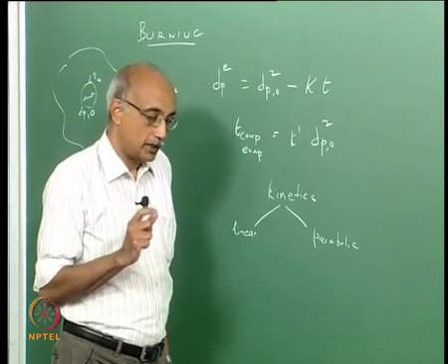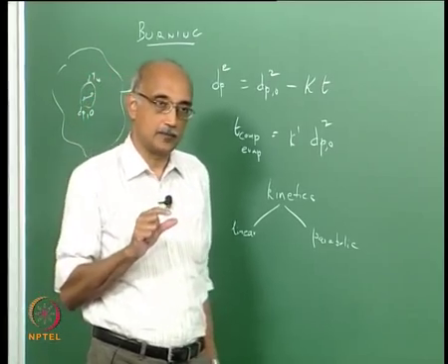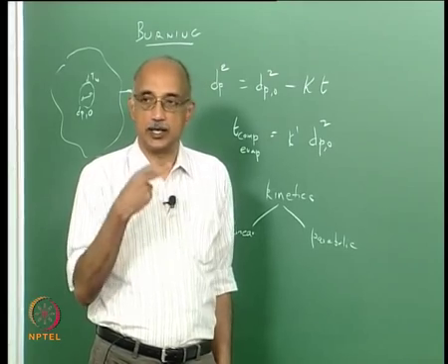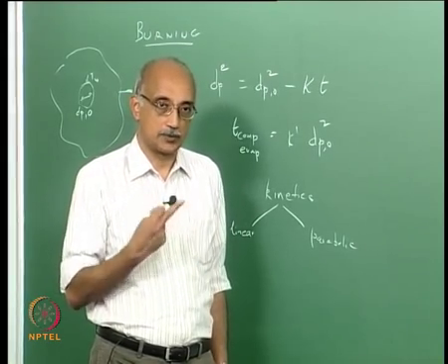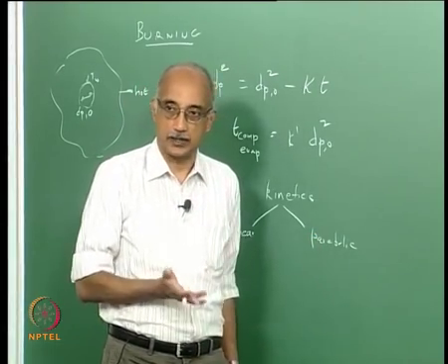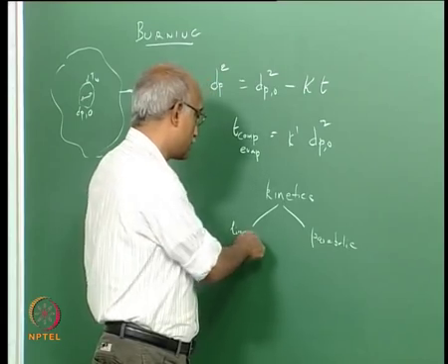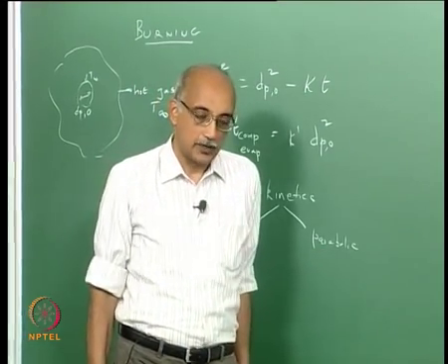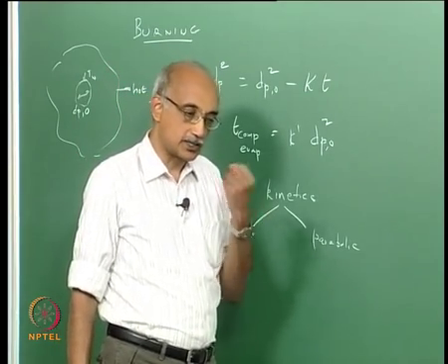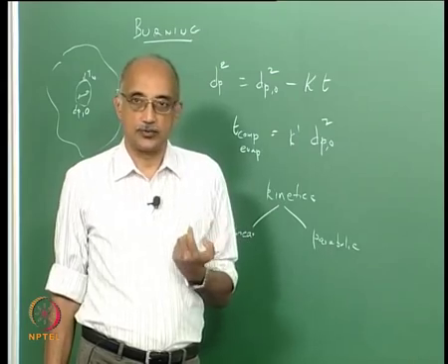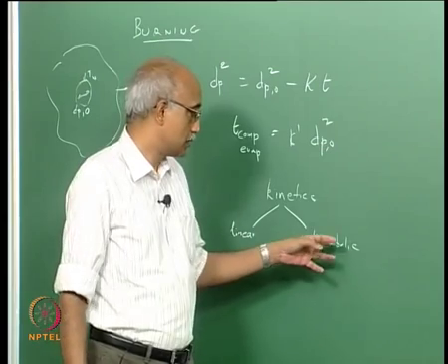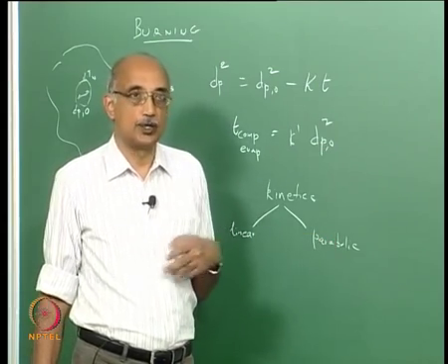So, the process of burning or the rate of burning becomes limited by the growth or buildup of this product layer around the external circumference of the particle or droplet that is burning. So, this introduces essentially a self limiting factor, and these two models are again widely used to consider the two different cases where you have an excess of oxidizer versus an excess of fuel. So, the linear model is typically applied when you have an excess of oxidizer, and the parabolic model is applied when you have a fuel rich condition.